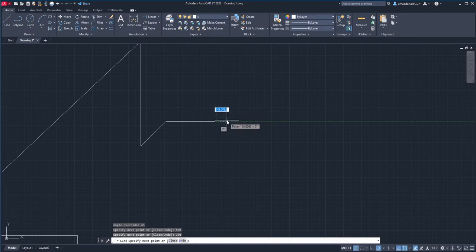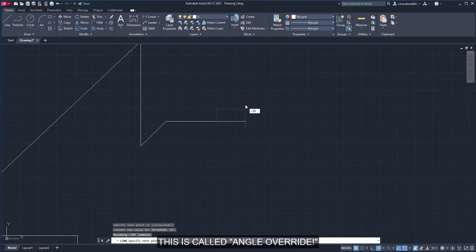So once more from the top, we're going to find the less than symbol, which is just to the right of the M. In this case, AutoCAD takes it to mean angle. You're going to hold Shift and then the less than key, so that'll produce the angle. We'll type 30, and hit enter. And now AutoCAD knows we want to draw a 30-degree angle.